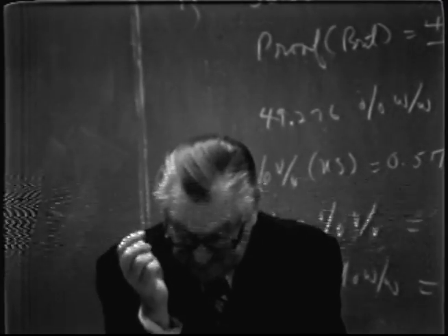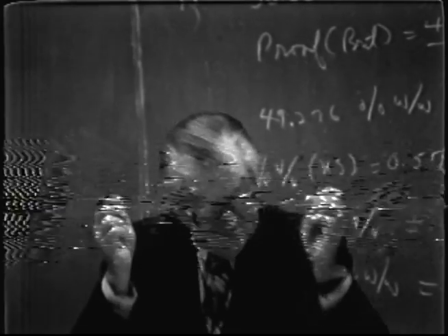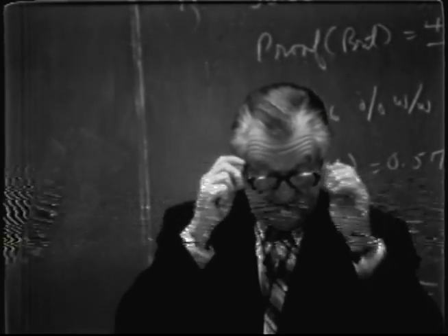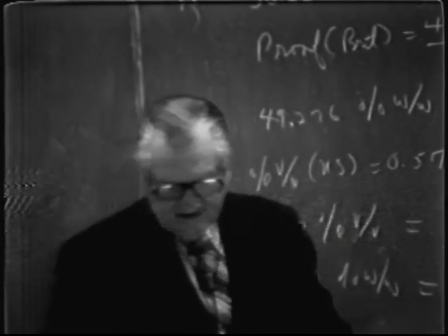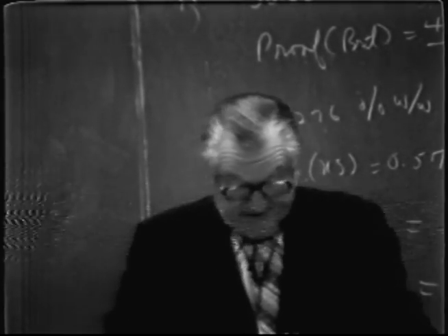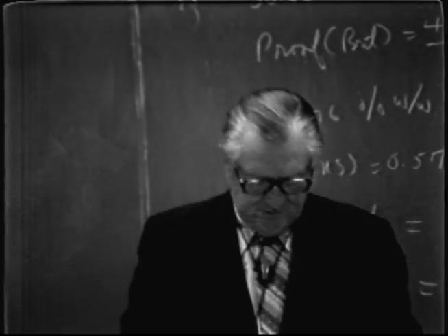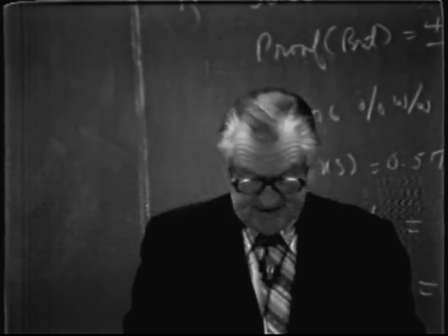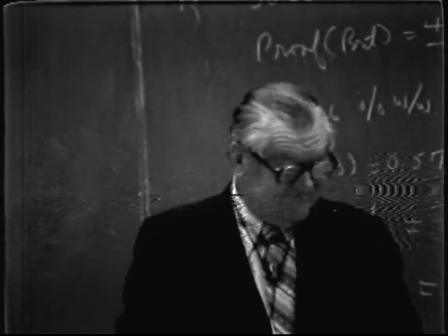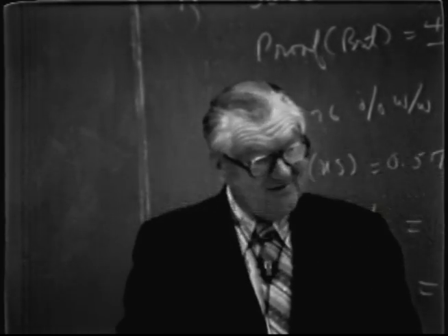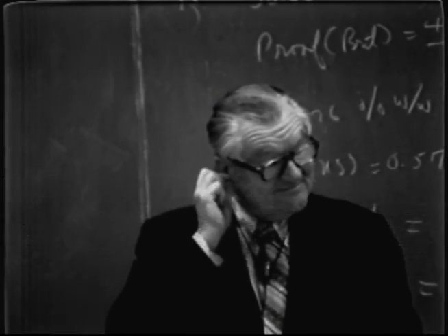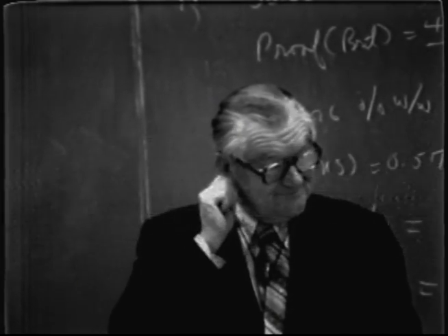I guess you have to use the rate here, 7,500 gallons per hour, and convert that to pounds of feed, and then if you know the percentage of alcohol in that on a weight basis, you get the pounds of alcohol, and then you divide the pounds of alcohol by the molecular weight of alcohol, and you have the pound moles.